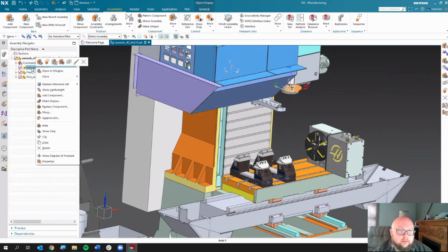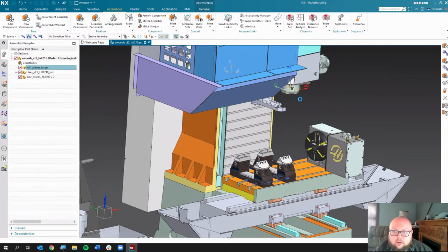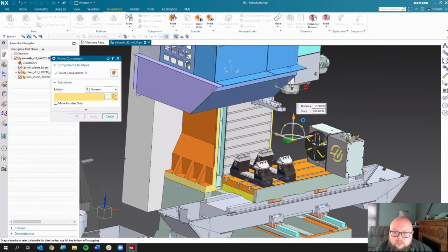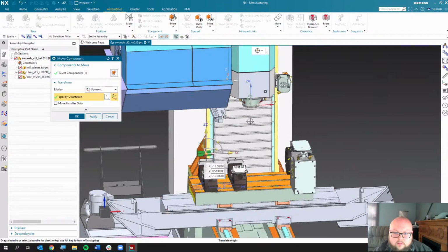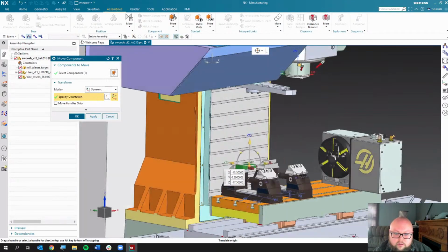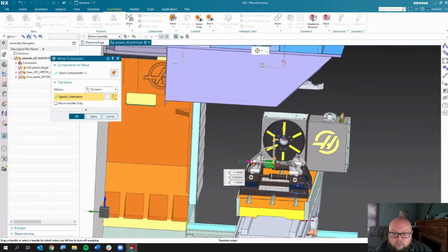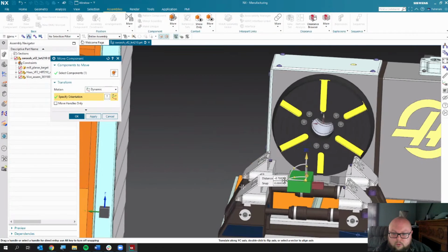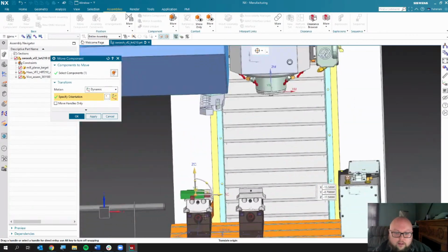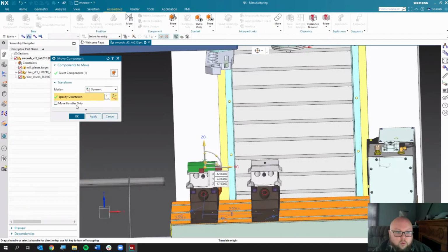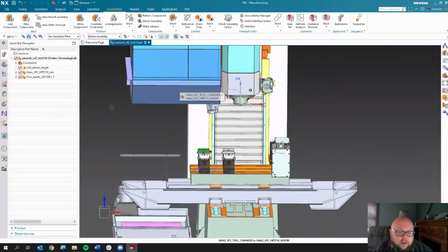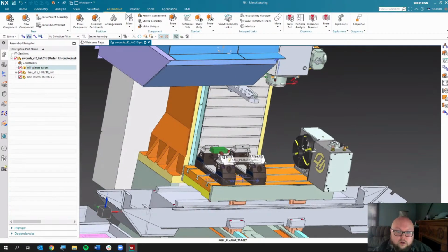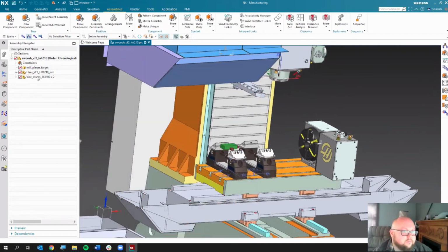I'm going to move this mill planar target. So I'm just going to move this part file so it's roughly centered in a vise. It's not too important. Again, this is geometry that gets replaced when you start a template. So it's really up to you whether you want to apply constraints or just have this roughly in location. I like to just roughly position it. And then once the actual component is brought into our file, once I am starting the setup, then I go through and constrain the part and the jaws and all that kind of stuff. We'll see that in future episodes.